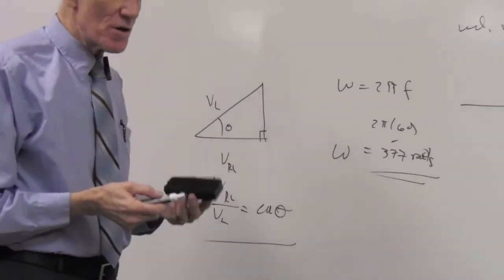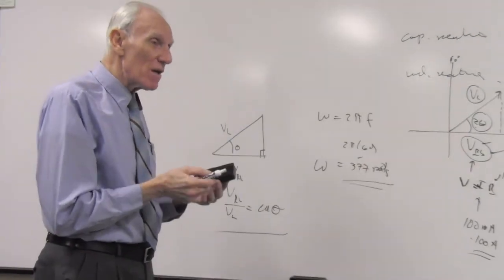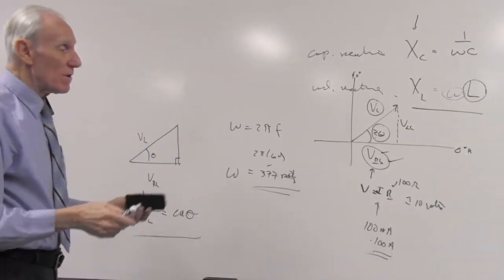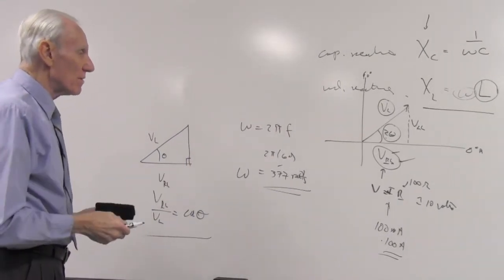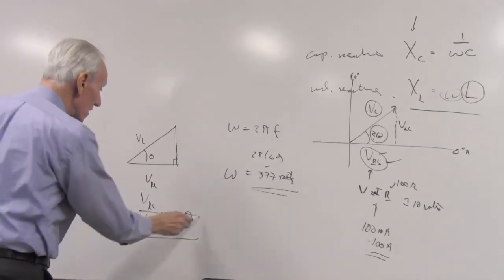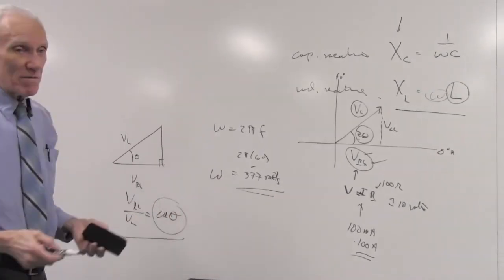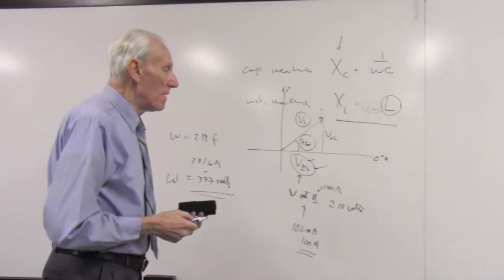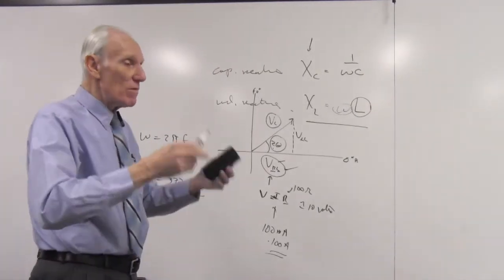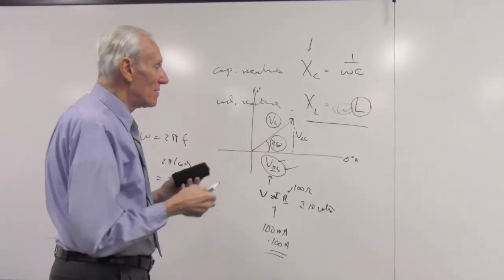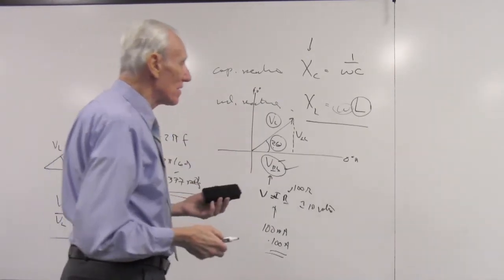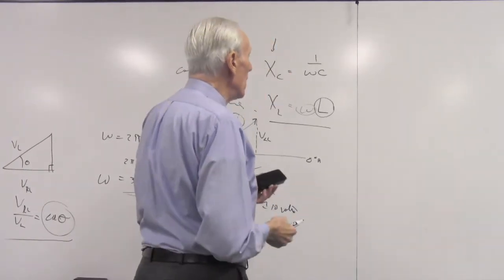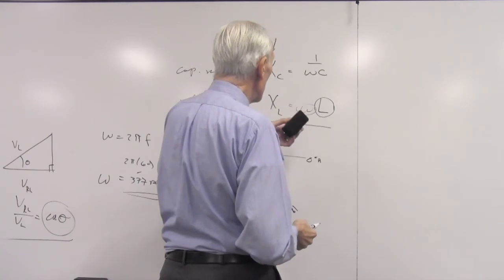And we're going to do this for two different currents, and the answer should be the same angle. It's the same inductor. It's got the same inductance, and it's got the same resistance, regardless of what current runs through it. And so it should be the same angle. So you're going to get two values for this angle, and I would average them to use that value in part C. Okay, so that's kind of running roughshod through the theory of capacitors and inductors in AC circuits. Again, the more elegant derivation is in your textbook, and is also in the handout, complete with every step.